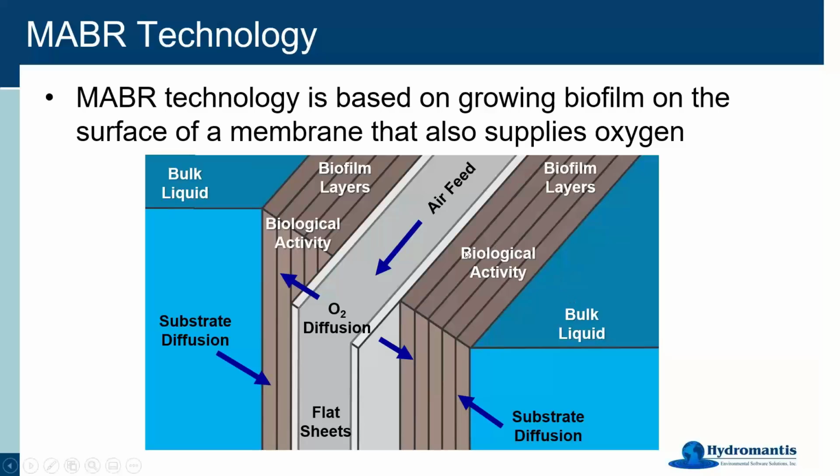Just for clarity's sake, the biological activity doesn't happen only in the biofilm. In our model, if you do have some biomass out there floating around in the liquid, it'd be much, much less than what you would have in the biofilm. But if you do have some out here, depending on whether you've got recycles happening or what have you, you will actually model all this the regular way that we normally model activated sludge.